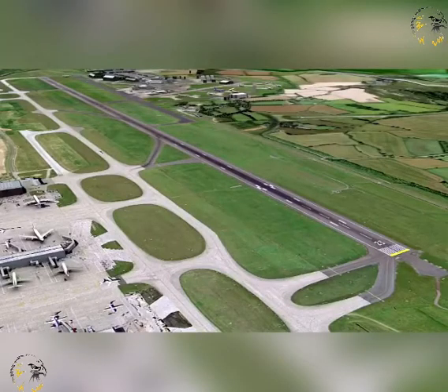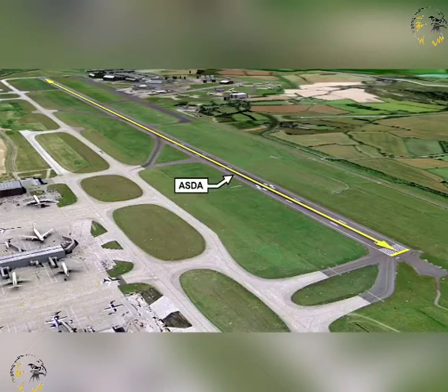The third of the specific distances at an airfield is the accelerate stop distance available, or ASDA. The accelerate stop distance available is the distance from that point on the runway at which the aeroplane can commence its takeoff run to the nearest point in the direction of takeoff, after which the aeroplane cannot be brought to rest in an emergency without the risk of accident.